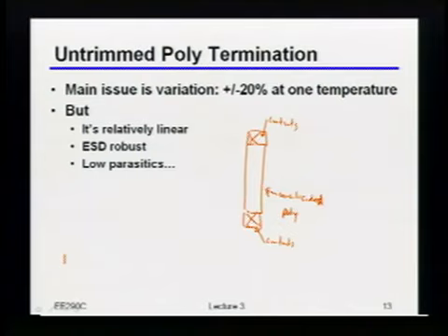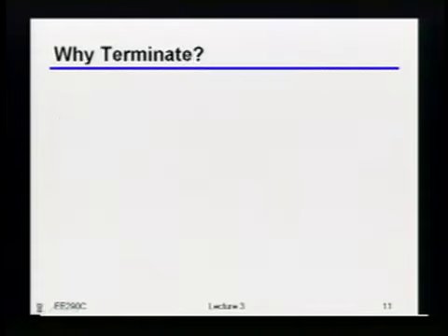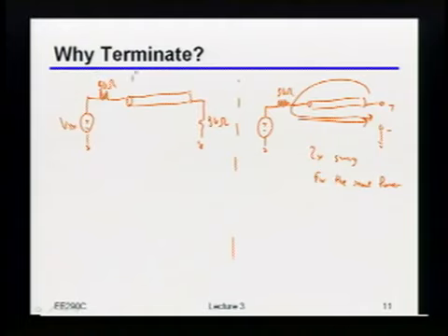Doesn't that actually change the termination which the chip sees? It becomes like 25 ohms, right? Oh, yeah, of course. You're absolutely right that if I looked at, for example, this equivalent model here, the impedance at that point is indeed 25 ohms, right? So when you design your circuit, you should expect to see 25 ohms there and not 50. By the way, just about anything that's terminated at the driver and terminated at the receiver, if both of those are 50, you're going to get 25 ohms at that node. That's just life. Which is another way of saying I have half the swing for the same current, right?